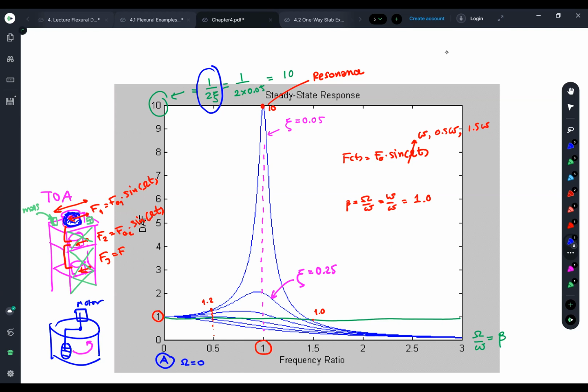It looks like I apply the force F. This is the time t, this is a force function. I apply the force F like this. Very, very slow. It will take maybe 1 year to go up and down. So in a time period of maybe 1 hour or 2 hours, in the unit of a second, you will feel very small change in the force function because the period is very, very long. The frequency is very, very small. If we take 1 day or 1 year to go from +1 to -1 in terms of the sine function.